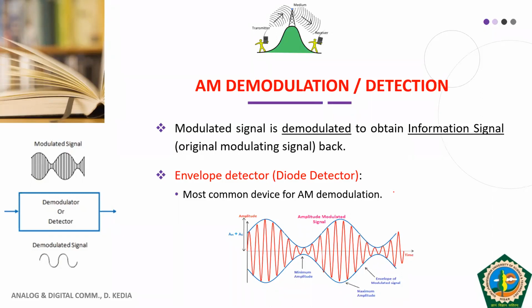Once you have understood single sideband generation, then vestigial sideband modulation is a very simple thing, because we know that in single sideband we removed one sideband and kept one sideband. Now in vestigial sideband we have one complete sideband and some part of the other sideband. So just by using a filter, we can add the vestige part and obtain the vestigial sideband modulation.